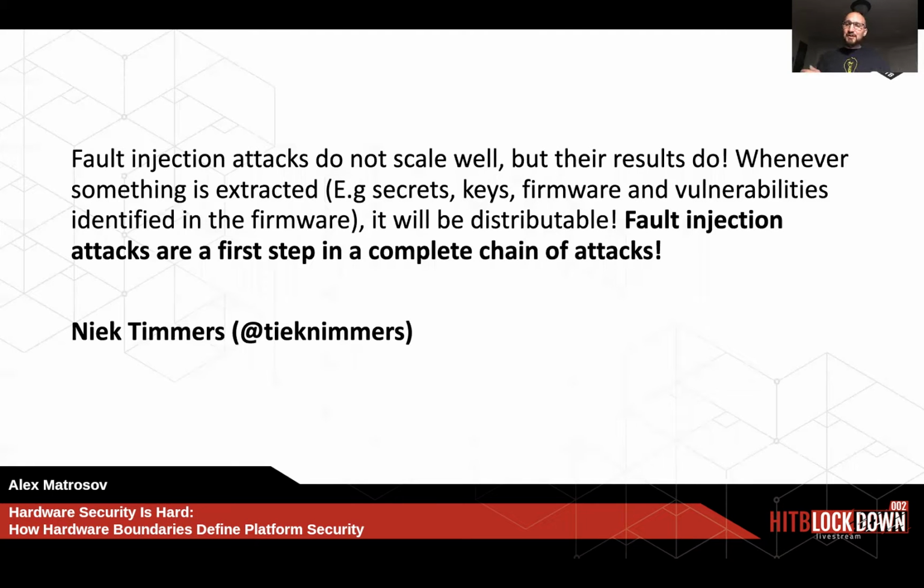Another thing I want to draw your attention to is fault injection attacks. A lot of small chips don't have good protection from fault injection attacks, like voltage glitching, electromagnetic fault injections, and many others, or power side channel analysis.